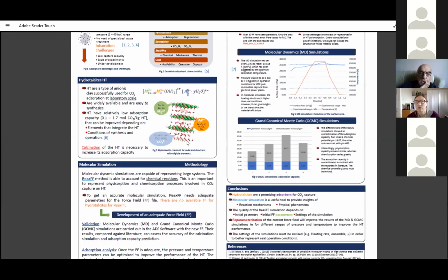Of course, if you increase the water much more, then it gets stuck with all the water and there's not so much carbon capture, but it's still interesting that even if you don't get rid of the water, it will capture CO2. Yeah, particularly if it's hot flue gas, you won't be able to get rid of the moisture that's in it. Yeah, that's another reason why we're trying this material: if it can work at higher temperatures, it can work with water. It is very sensitive to sulfur oxides, but we're working on the case of a natural gas-fired power plant, so we're trying to simplify things for the moment.